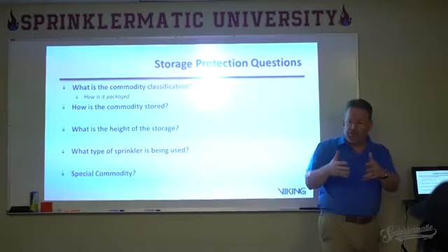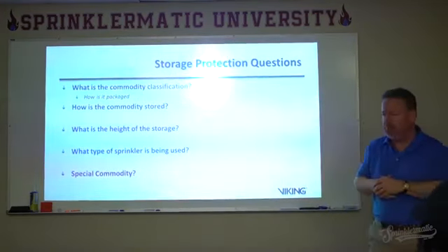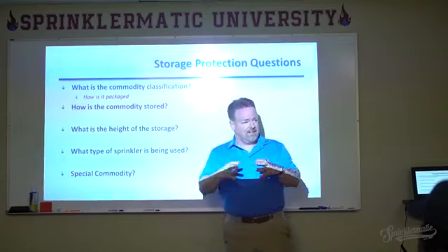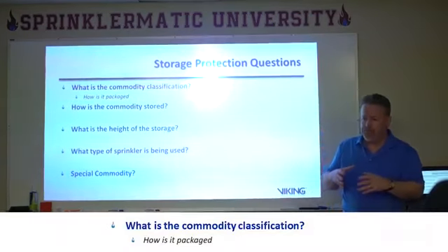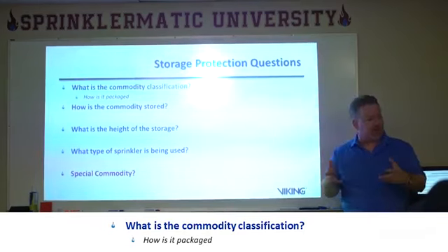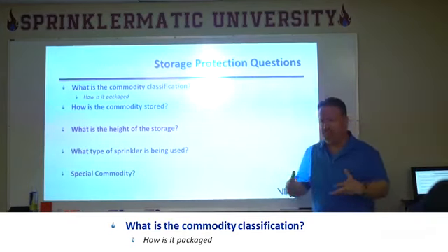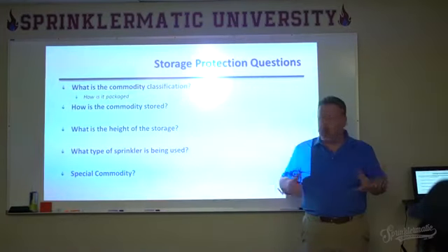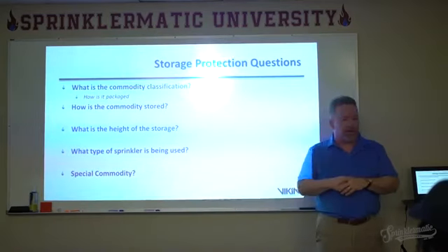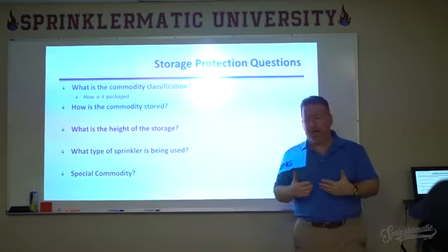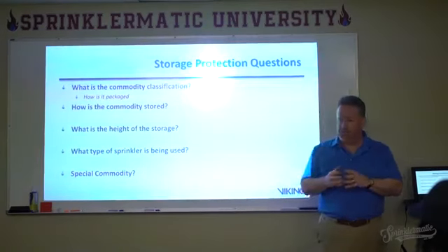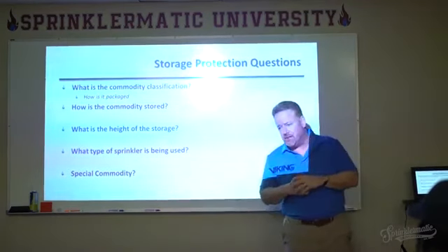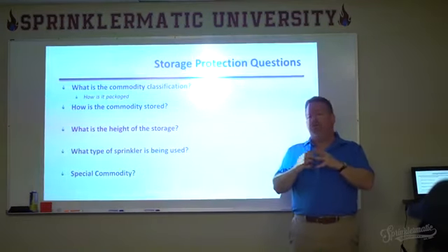What is it that's going to burn in this particular arrangement, the storage warehouse or the storage area? Now, a subset of that is also, how is it packaged? Because if we take something that's non-combustible, a steel desk or a steel washing machine or something along those lines, that's not going to burn very well at all. But if we put it in a multi-layer cardboard box, it might have a different characteristic. If we wrap it in plastic, it might have a different characteristic. So we need to be careful with that.